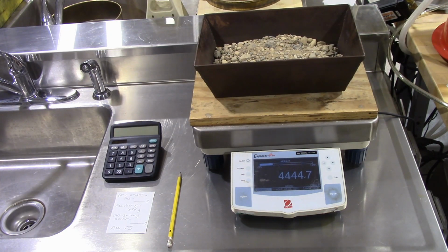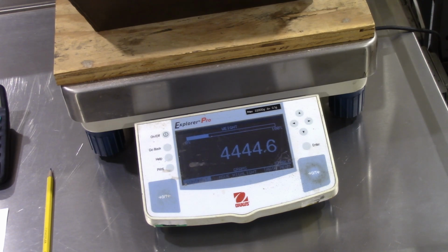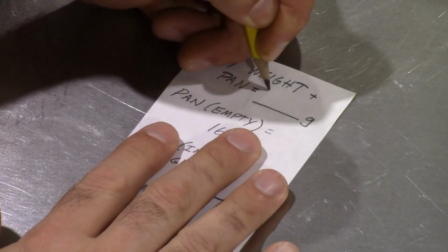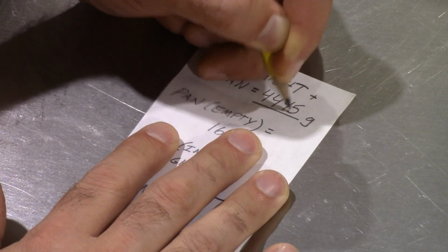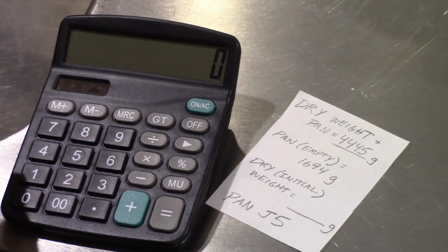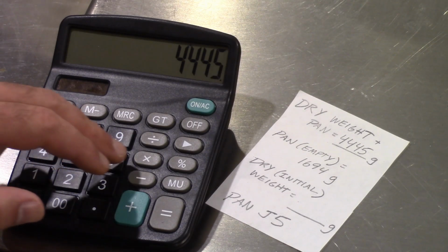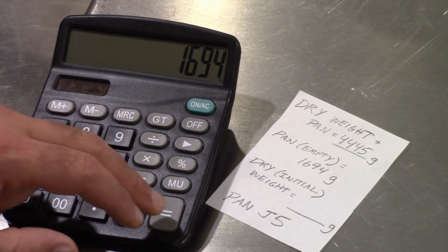Place the cool sample on the balance. The sample should be easy to handle without the use of gloves. Allow the balance to stabilize and record the value to the nearest gram. Note that the balance readout displays the weight of both the sample and the container or pan used. You can elect to weigh the empty pan prior or after the test, but it must be accounted for at some point.